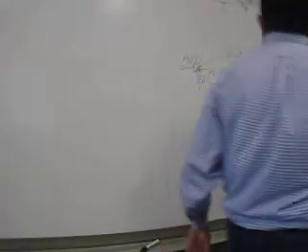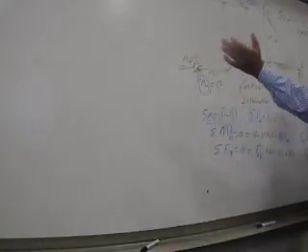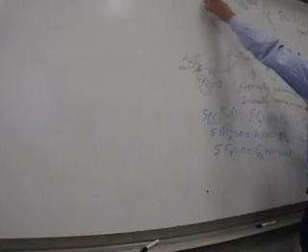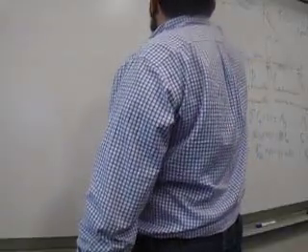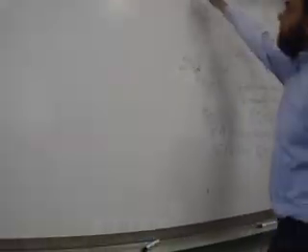Again, I'm taking a moment here. I know the Ay is 0, so it's out of my equation. I know 60 times 15, Cy times 15. Acting with them is the 60 times 5. Therefore, Cy is equal to, this 15 goes away this way, and this will be 4. So this will be 20 plus 60, this will be 80, but it's a negative 80 kips. It's going down.